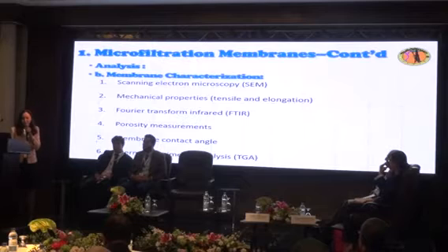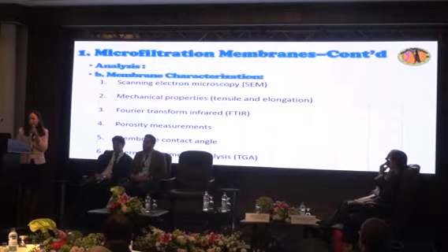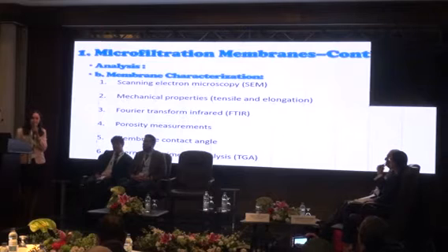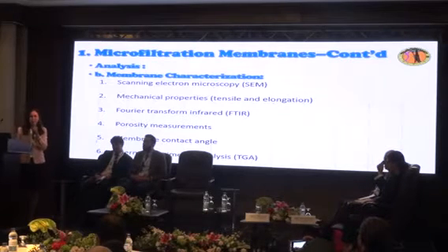Also, I make some membrane characterizations, like scanning electron microscopy, and also the mechanical properties, tensile and elongation stresses, FTIR, porosity measurements, which is the main important factor we need, because we need to gain small pores at the same time.